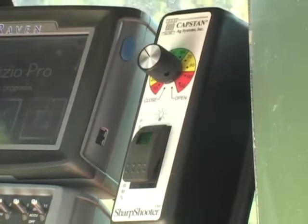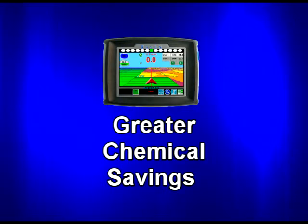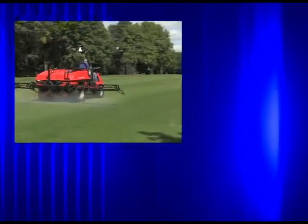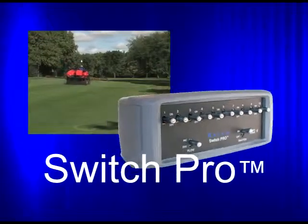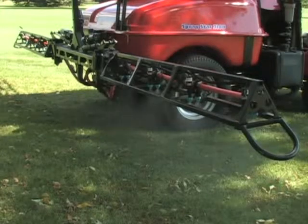Using Sharpshooter as the foundational technology, Capstan Turf Systems adds an option for an advanced rate controller, the Invisio Pro. Invisio Pro provides the opportunity for chemical savings by minimizing overspray and overlap applications. It also provides a record of the application that can be downloaded to a computer for future use. To achieve those values, the Invisio Pro rate controller comes with an internal GPS that's coupled with Switch Pro, a 10-section switch console, and AccuBoom, an automatic section control software. This total system adds to Sharpshooter's ability to control flow and pressure at individual nozzles.